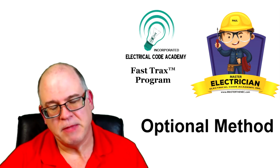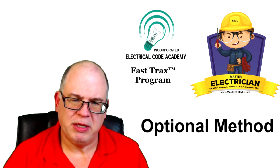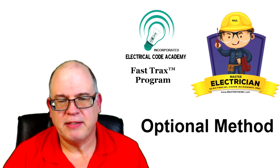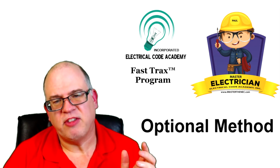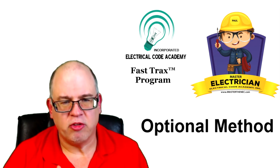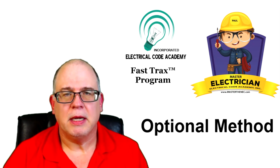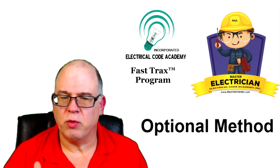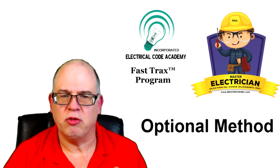We'll see. But I'll tell you up front, today's presentation is going to be on the optional method, doing the calculations for a single family dwelling. We have already done a presentation on doing the standard method, and that's available on our YouTube channel. It goes into all of the things that you need to know to do the standard method, which is part 3 of Article 220. But it also talks about sizing the neutral conductor. The reason that's important is because when you're doing the optional method, you don't use the optional calculations for the neutral. You have to use the standard method.